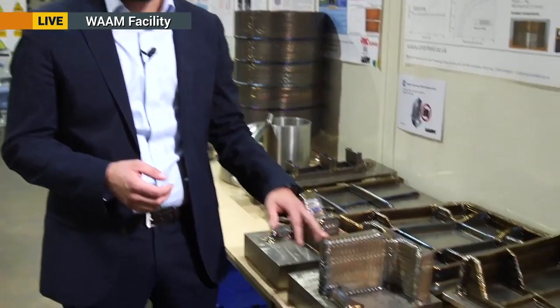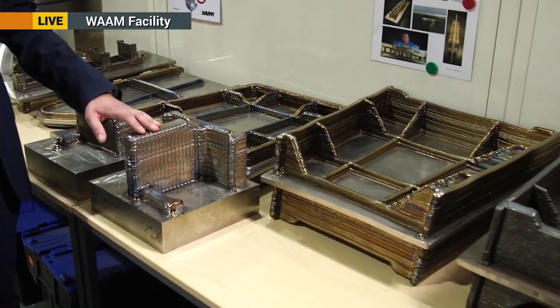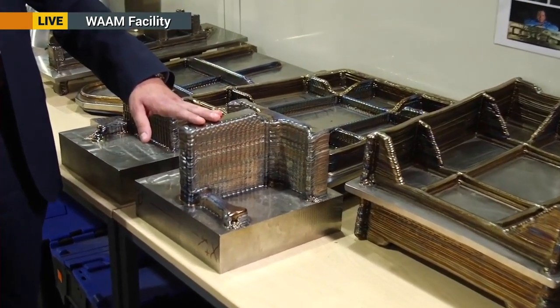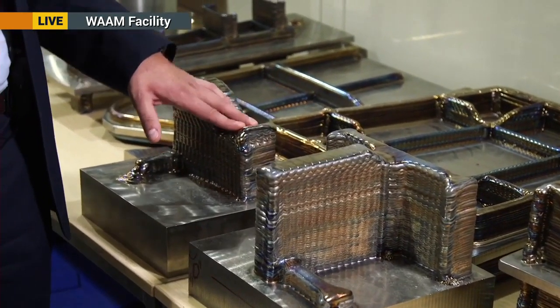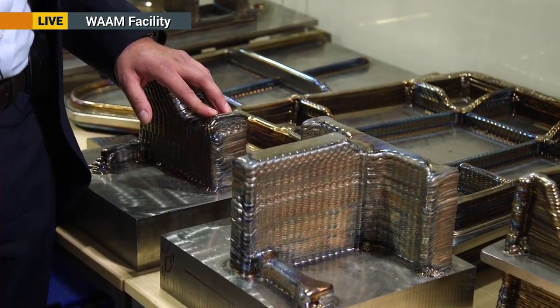Having said that, there has been quite the upkeep of WAAM in industrial design and civil engineering, and I think early next year a bridge which has been 3D printed will be installed in the red light district in Amsterdam actually. Wow. So WAAM is getting out there, and at this point in time we are working very closely with the OEMs, for example in this case aircraft manufacturers. We are about to start making a 200 kilograms landing gear rib in one of the cells here on campus in this building, and before we started with the proper manufacturing of this landing gear rib, we've done a couple of test pieces to make sure that certain features could be produced with the required integrity, and that's the typical journey that we put in practice.